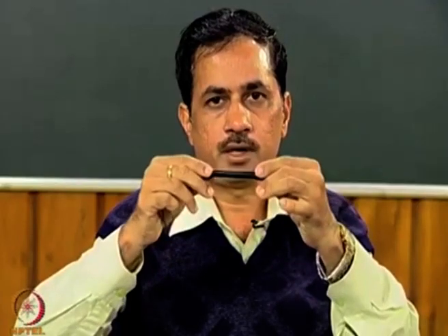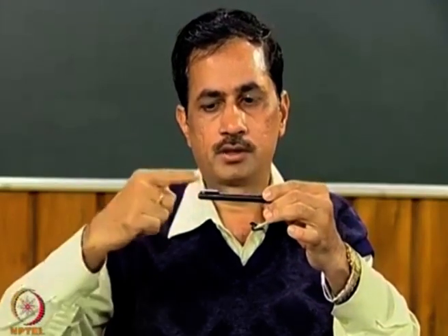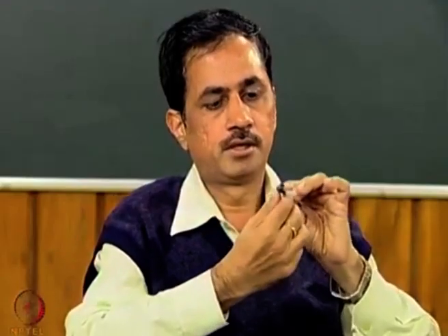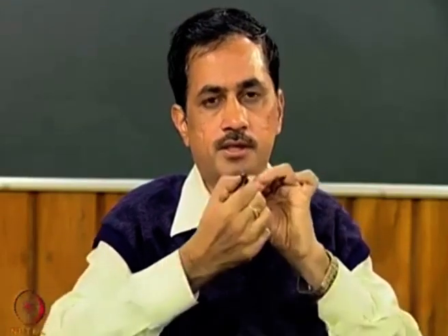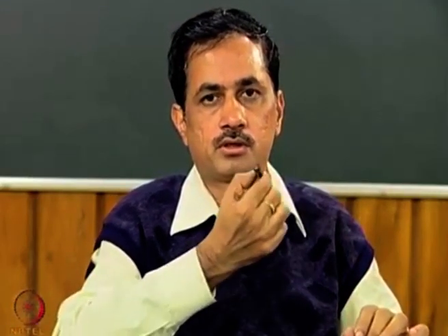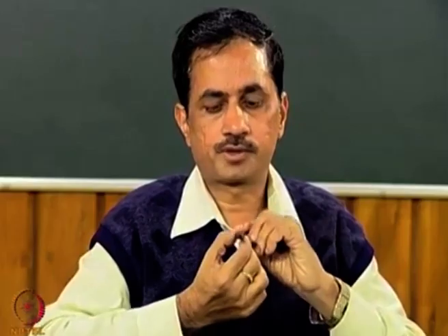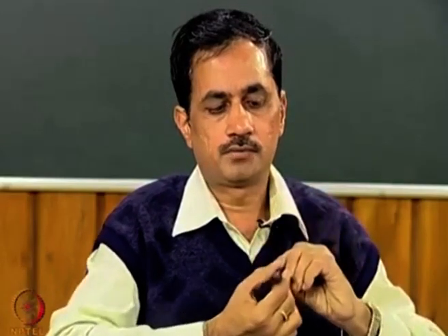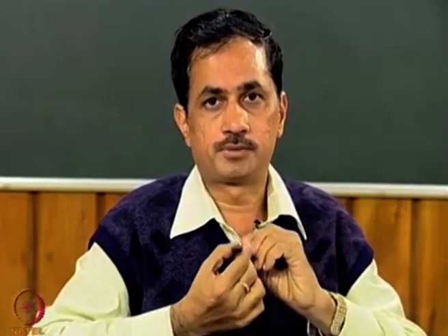The whirling path, if we see from this side, is elliptical. So this is the motion we obtain as an elliptical path in the x and y directions. Not only is it spinning, but it is also whirling, and the whirling motion is in an ellipse.